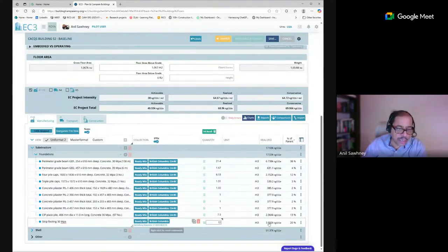And it automatically calculates the GWP. And if I want to go back and see which particular EPD I applied to this one, I can see it here. So it's a pretty straightforward process. You will search for the category, look for the location, search the right EPD, and say, use this collection. It brings and applies it here. And you can continue to do this. I'm only doing it for concrete, but you can do it for rebar, structural steel, paint, floor, tiles, and most of the materials that are going to be used in constructing this building.